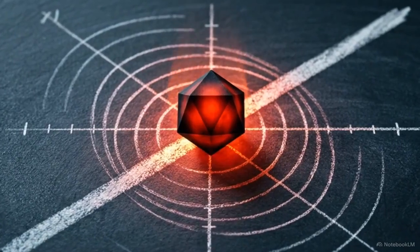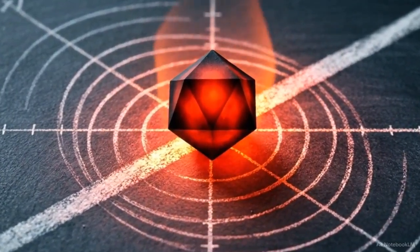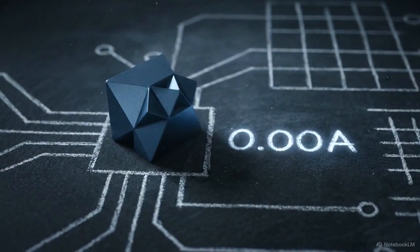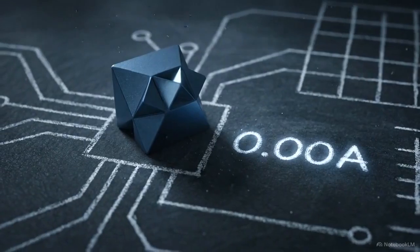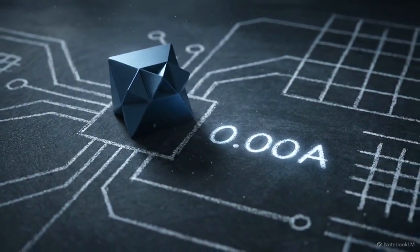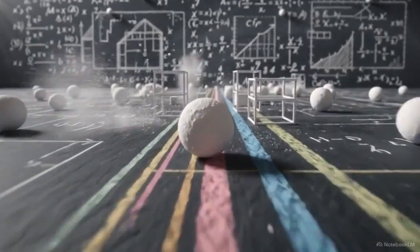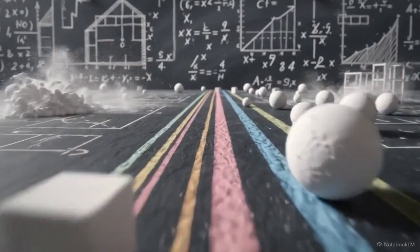Resting in the center means the transistor is always drawing current, which provides high signal fidelity at the cost of poor energy efficiency. Conversely, resting at cutoff means the transistor draws zero idle current, which maximizes efficiency but sacrifices half the signal data. Engineers select an amplifier class to balance the trade-off between signal purity and power consumption. By mastering the mathematics of the DC load line, you gain precise control over the fundamental limits of analog electronics.